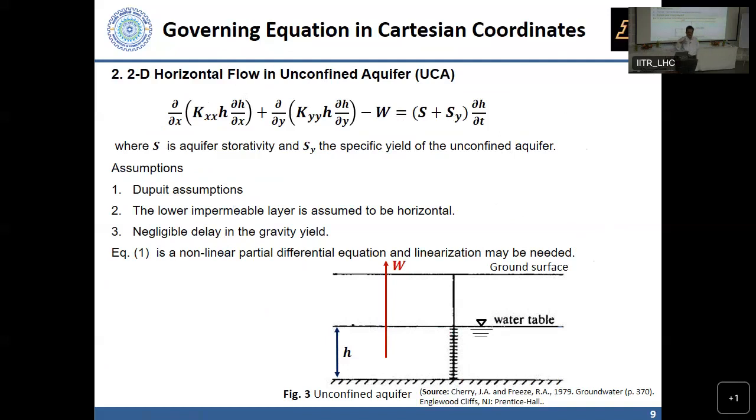doesn't release easily. So that fraction that it does not release easily is sometimes called a specific retention. It's retained by the soil. So the total porosity is usually considered as a combination of S sub Y plus the specific retention. Then S for storativity. S sub Y just tends to be usually a couple of orders of magnitude larger than S, for unconfined aquifers.